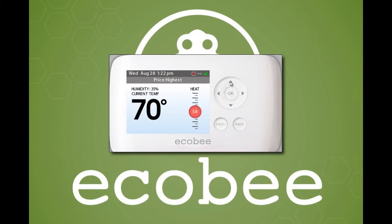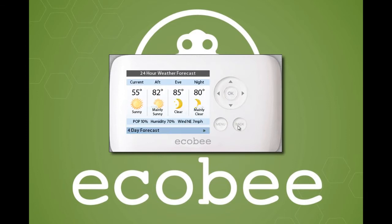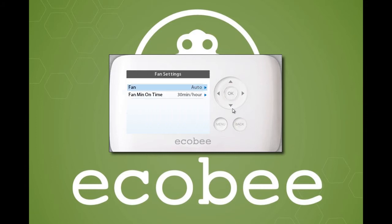To make a change to the set point, press on the arrow up or arrow down. This will put the thermostat into the hold action. By pressing OK, it will resume back to your 7-day schedule. To access further menus, press the menu button. Here you will have the option to view your weather forecast, change system mode, adjust fan status, adjust your weekly schedule, set up reminders, alerts, and so forth.